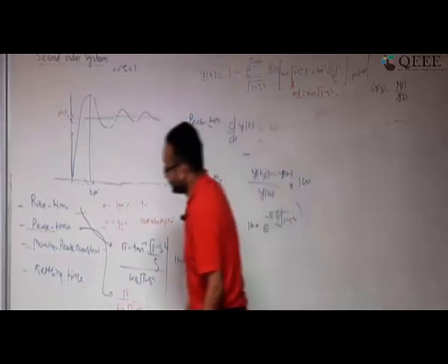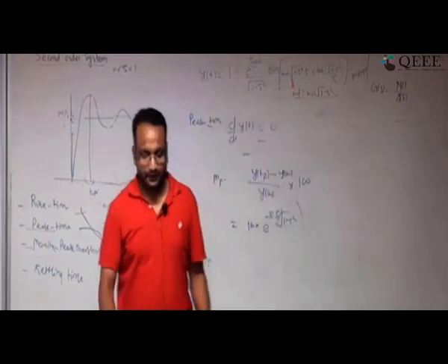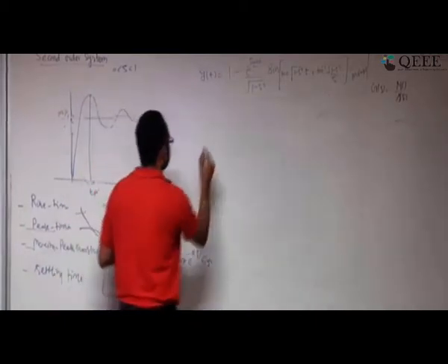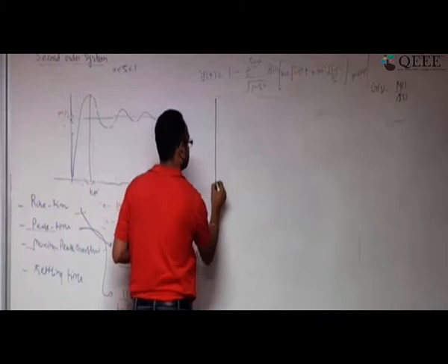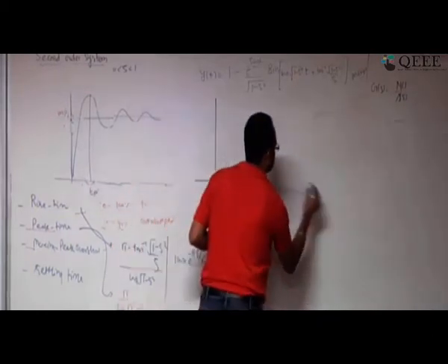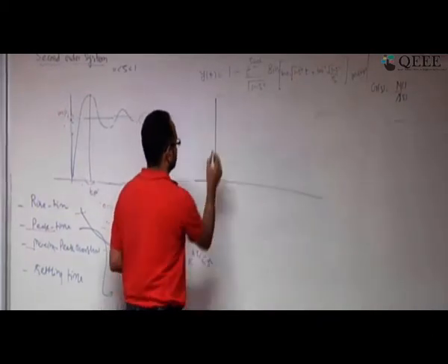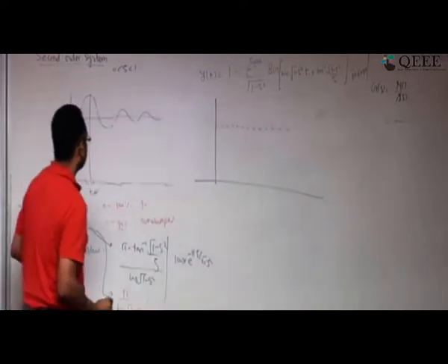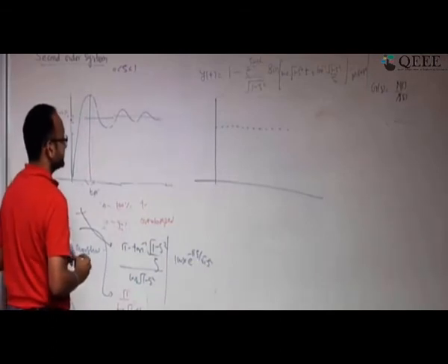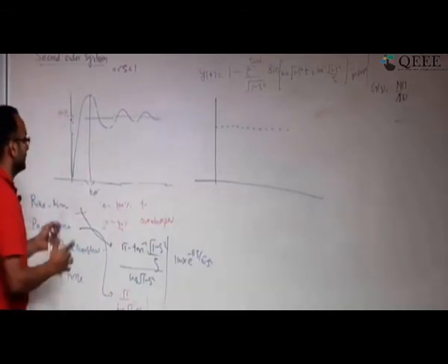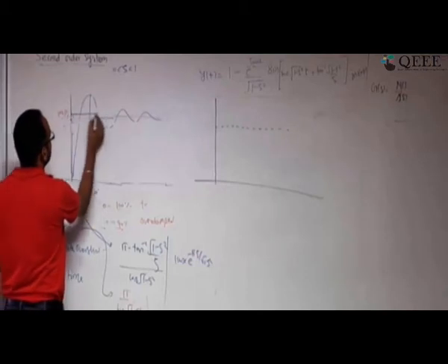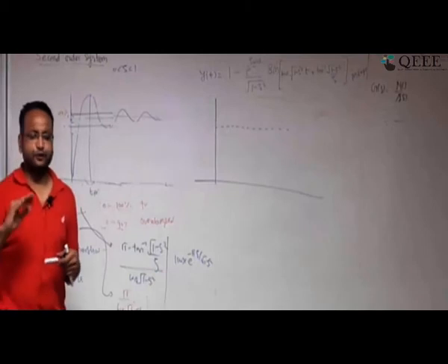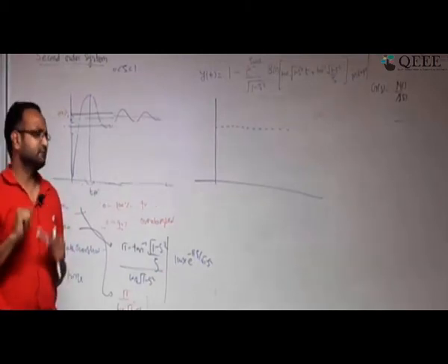Now the very important term I want to take is settling time. To explain this, let me use this plot. Settling time is, as I define it, try to understand, I will define a tolerance band. The tolerance band is generally defined as 2% or 5%, it is well known.